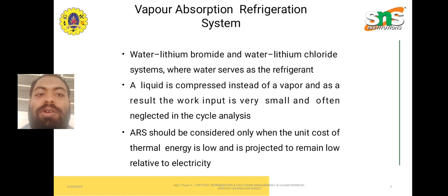Here we can see the water-lithium bromide and water-lithium chloride systems, these two systems where water itself is the refrigerant. A liquid is compressed instead of a vapor, and as a result, the work input is very small and often neglected in the cycle analysis. ARS should be considered only when the unit cost of thermal energy is low and is projected to remain low relative to electricity.